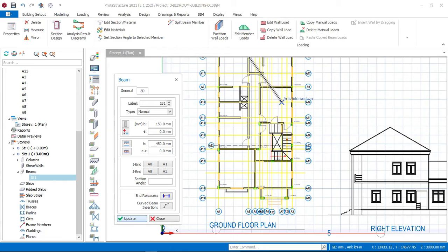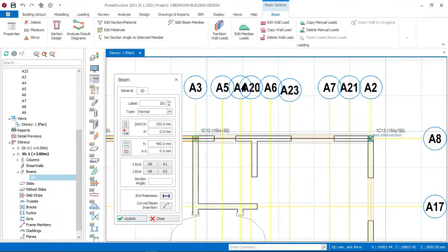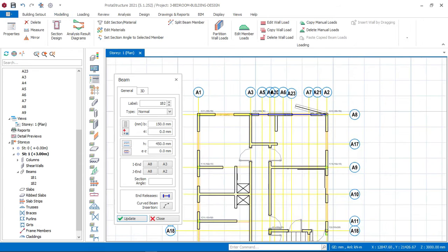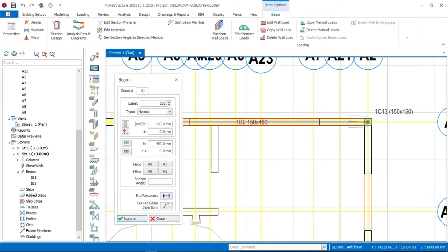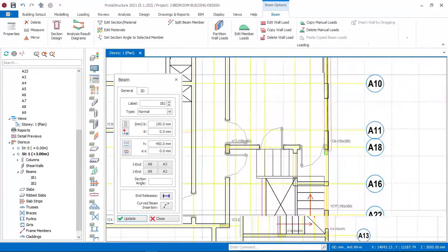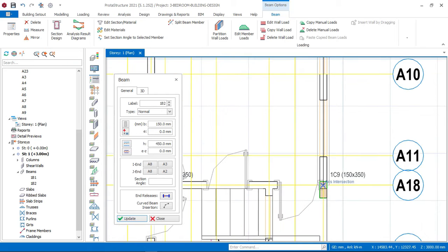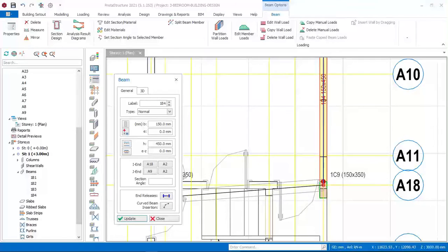Now on this update right now, I will now begin to click on other places. As you can see what I'm doing right now, you can now see that all the beams have now fit into the size of the wall. So I'll go ahead again and click at this very point here. Since I have a column here, it will try to terminate there. So I'll just click here right now, and then let me just remove this free end.